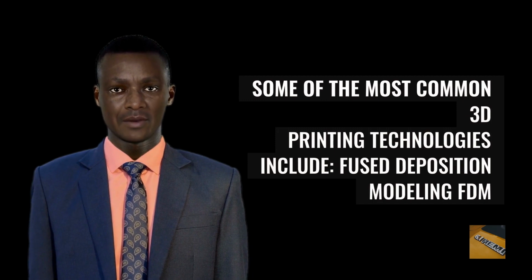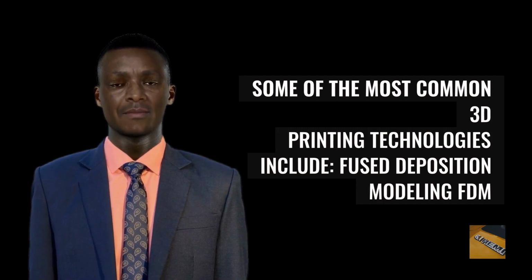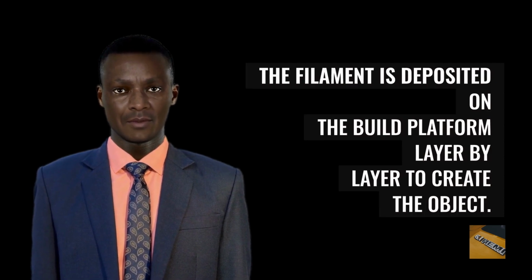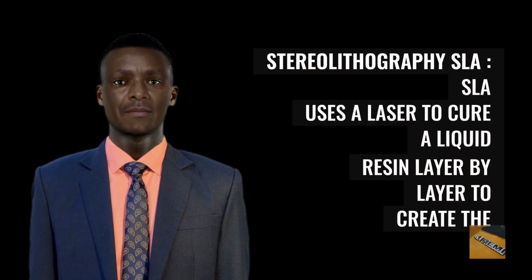Some of the most common 3D printing technologies include fused deposition modeling (FDM). FDM is the most common type of 3D printing technology. It works by extruding a melted thermoplastic filament through a heated nozzle. The filament is deposited on the build platform layer by layer to create the object.